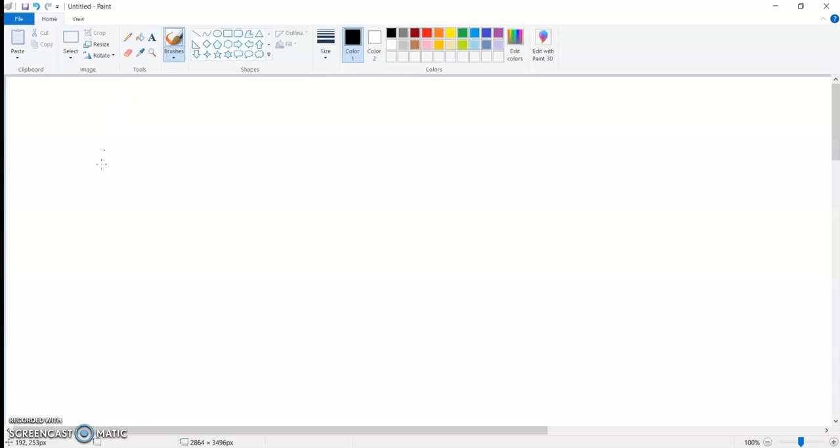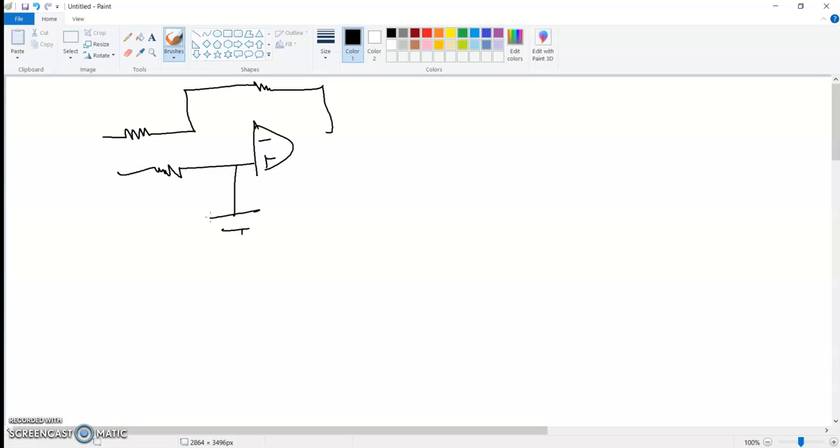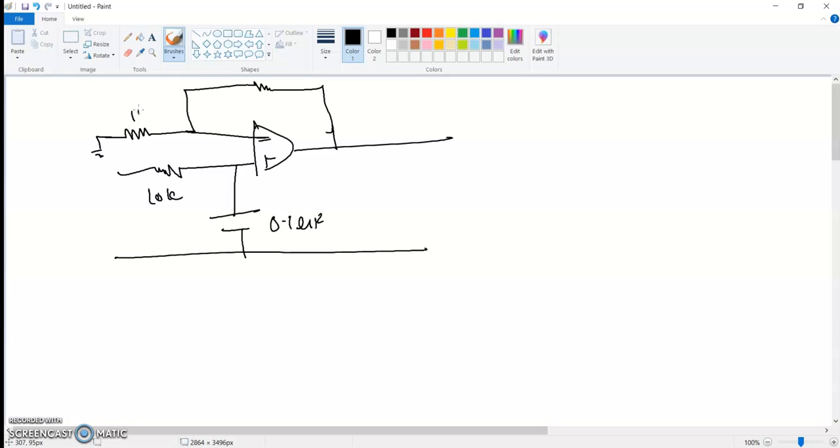Suppose I have a circuit with negative, positive, a resistor again, and a capacitor over here. That's my output, that's my input, and that's my ground. It's 10 kilohms, it's 0.1 microfarads, 1 kilohm, and 4 kilohms, and it's an active low pass filter. Tell me the value of the cutoff frequency and the value of the gain. Straightforward.